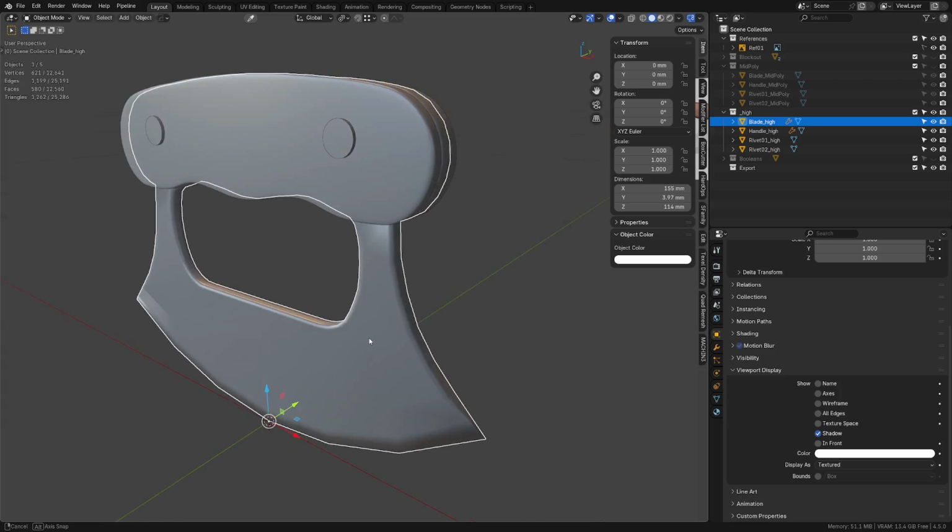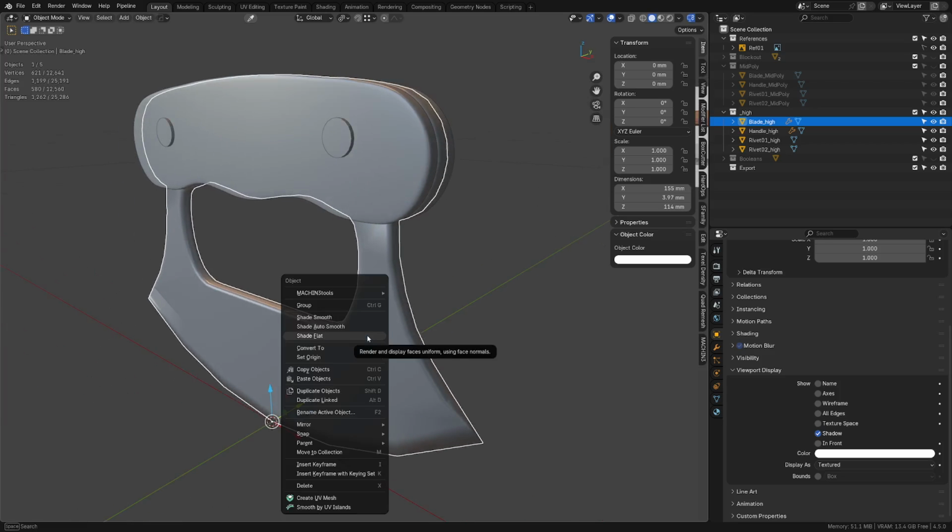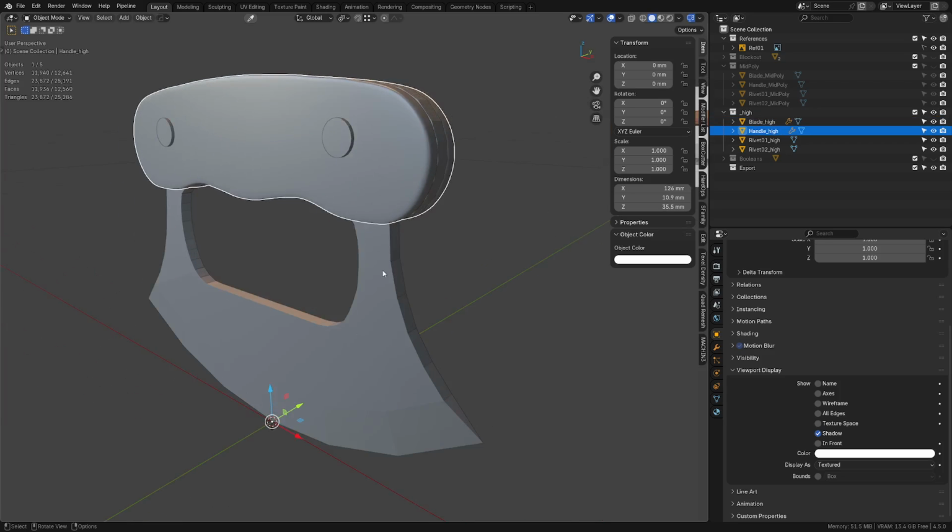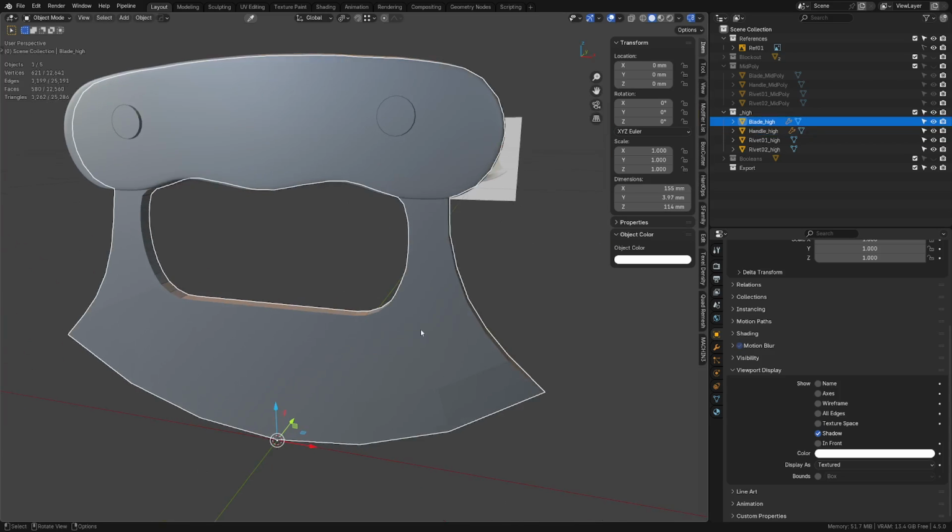It's shaded smooth right now. It's not ready for that. I'm going to shade it flat. Generally when I'm working on something, I'll use flat shading, try to get the topology correct, and then I'll worry about the shading a little bit later on, perhaps. As long as the topo is good, your shading should be mostly good as well. But if you want to turn it on or use auto smooth in the process, that's on you. All right, I'm just going to leave it off for now.